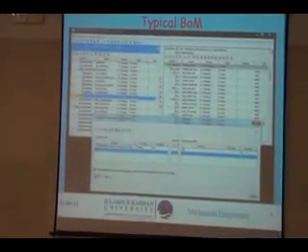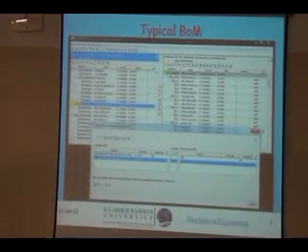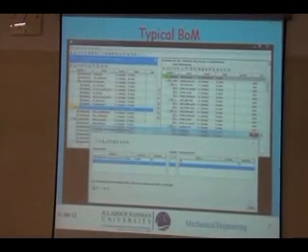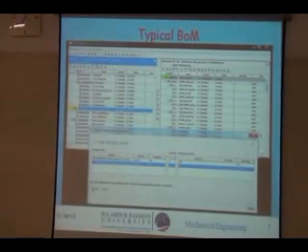Please view carefully. This is a typical bill of materials when you work in Pro Engineer. Pro Engineer facilitates this. When you assemble in Pro Engineer, you make hundreds of components. You assemble them to have a sub-assembly. You assemble sub-assemblies to have the assembly. When you prepare an assembly, automatically the BOM is created. The computer does it.